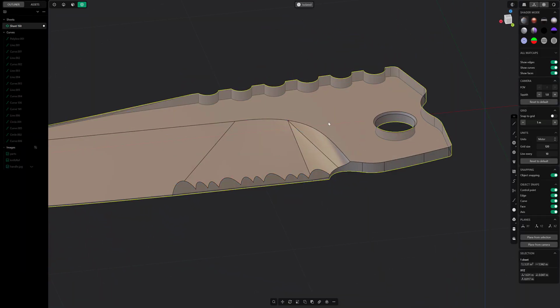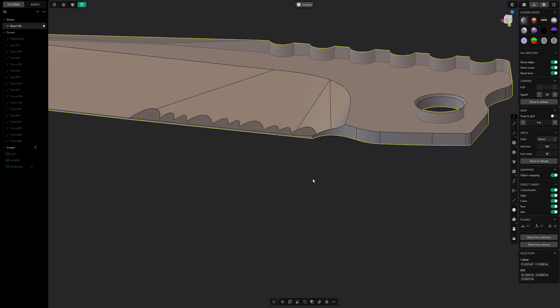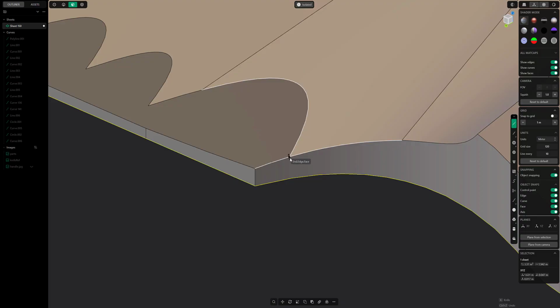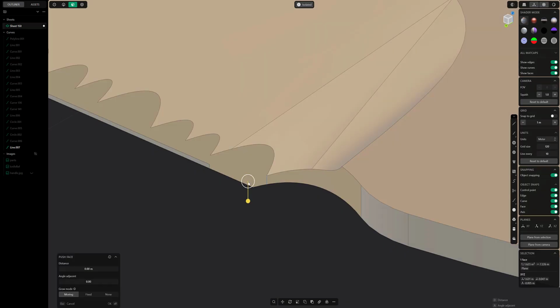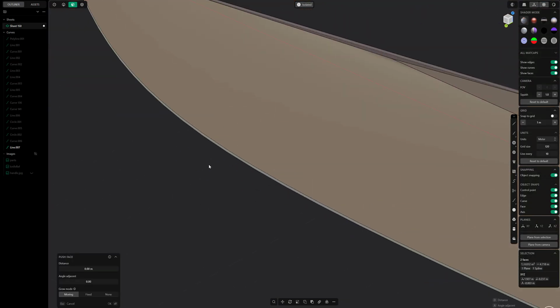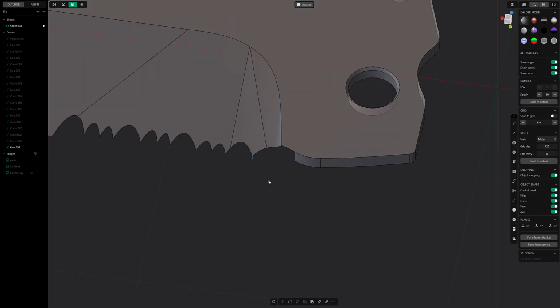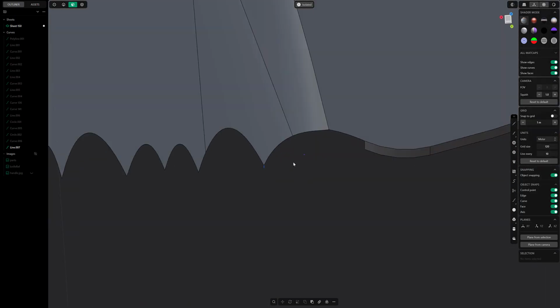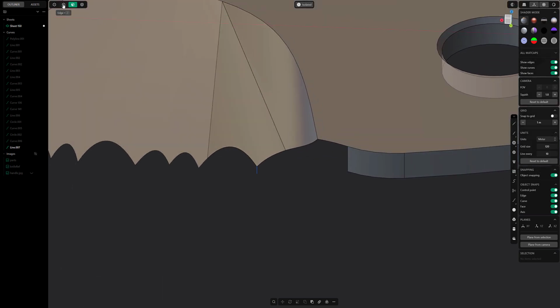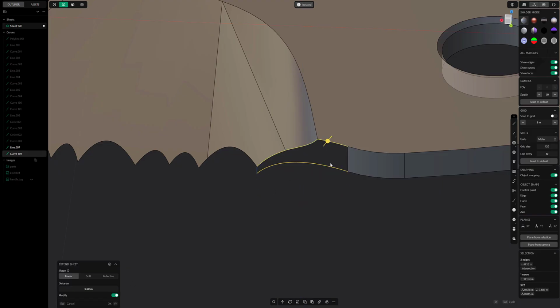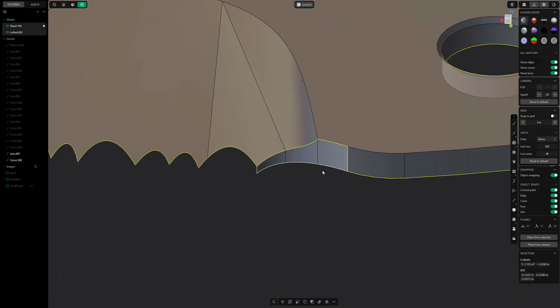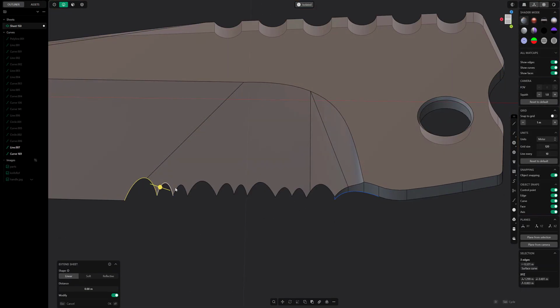But once I have that shape, I now need to get rid of the thickness and the back part. So this has to be redone. I need to draw this in here so I can get rid of this face. And then I need to get rid of the back part too. Right now there's not a sharp part of the blade, so I need to create that. With this new edge in, I need to fill in this gap. I select the same edges, duplicate them, and Z smash them down to 0, and then put them into place, and then we just loft them with G0, and join it with the main body.